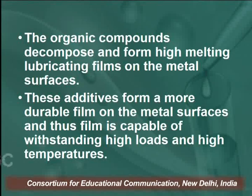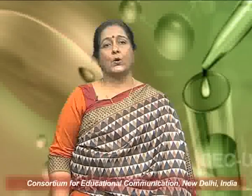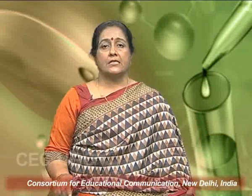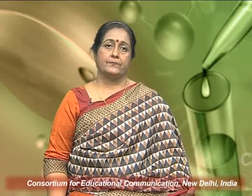These additives form a more durable film on the metal surfaces, and thus the film is capable of withstanding high loads and high temperatures. As discussed before, these additives are organic compounds having active radicals or groups such as chlorine as in chlorinated esters, sulfur in sulfurized oils, and phosphorus as in tricresyl phosphate.